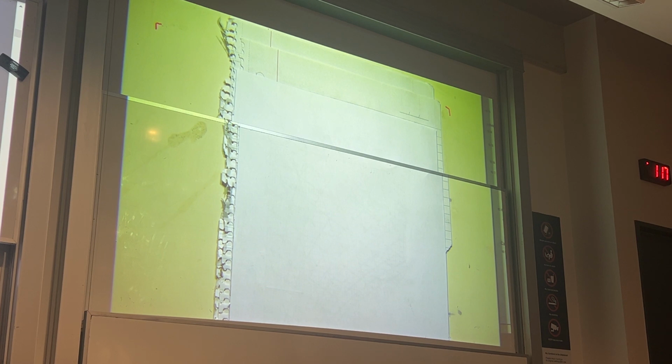So, like I said, they'll step you through these questions. So, part 1 is just looking at our gas turbine. So we're given all this information up here, and then overarching we have 375 megawatts of work. So first up we want to know the back work ratio. So we want to know the ratio of our work in to our work out.